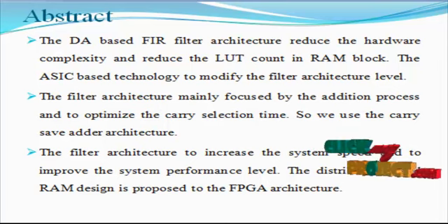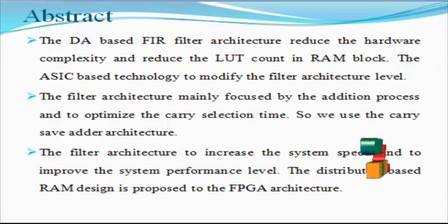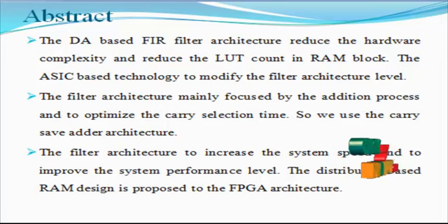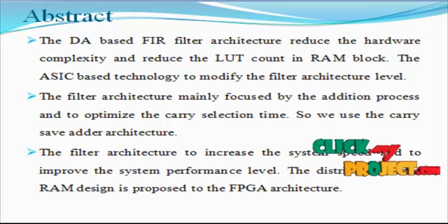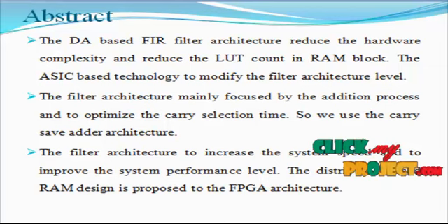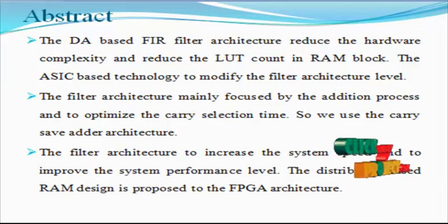The proposed design involves 68 and 58% less area delay product and 78 and 99% less energy per sample than DA based systolic structures. The carry save adder technique is used for the ASIC realization of the DA based reconfigurable FIR digital filter architecture.